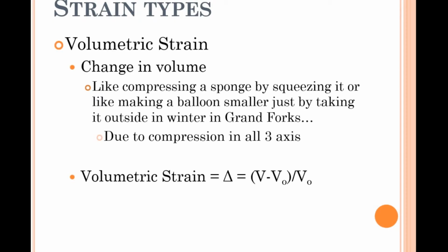So you covered before there are a few kinds of strain. There's volumetric strain. The whole thing shrinks or expands depending whether it's compressive or tensional. It could be you have a sponge and you squeeze it. It gets smaller because of the compressional stress. It could be a balloon. Take a balloon and dunk it underwater. First of all, kind of hard, but second of all, if you get it under there, it'll actually compress because of the stress, the pressure on all sides of the balloon.